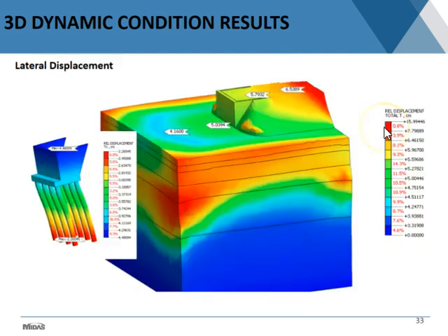Now, with this type of model, you can also get results in terms of bending moments and lateral displacement of the piles. And if you compare 3D against 2D using Midas, you see a reduction of about 20 to 30%. And that's because not all the displacement goes to the bridge. Some of it just goes away from it. So you don't get the full demand of a 2D model. You get less than that. And in this case, for this analysis, the reduction was about 20 to 30%.